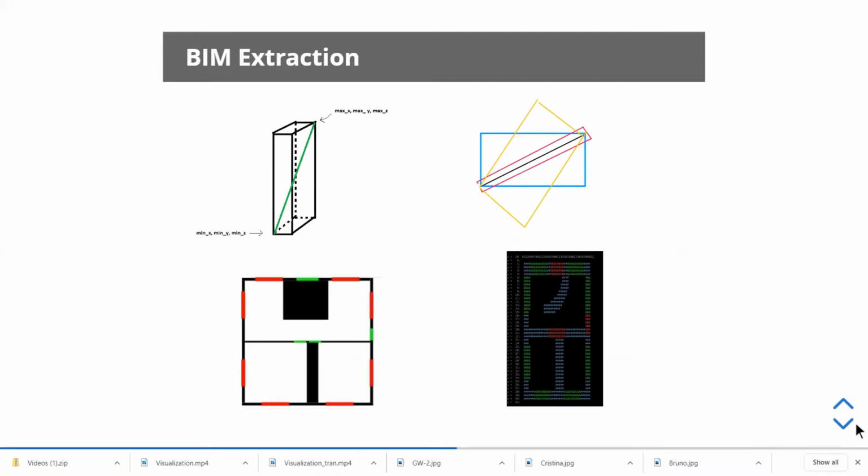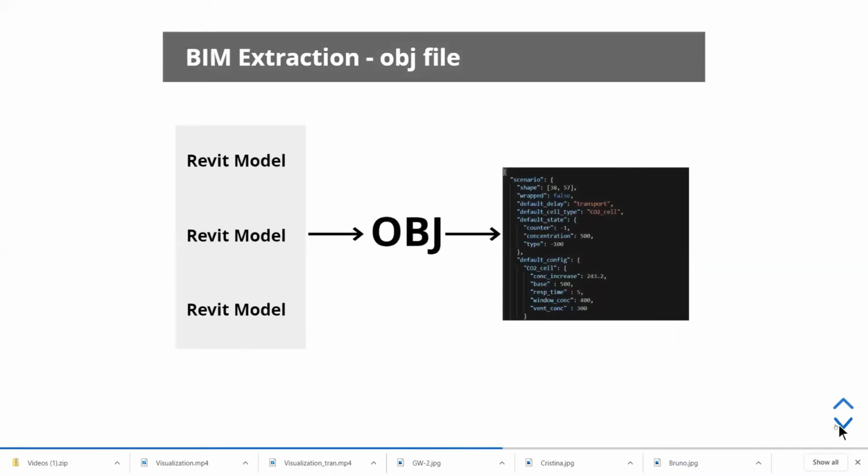And for that, after a few tries, we landed on using Autodesk's derivatives API. And so the process is now: take the model that we care about, get the file manifest, find the database for all of the properties, and work out what IDs belong to walls or doors or windows or whatever other elements we care about for the purposes of the simulation. And then we send out derivative job requests to Autodesk's servers asking for OBJ files. And once those are finished, we download them, open them up.